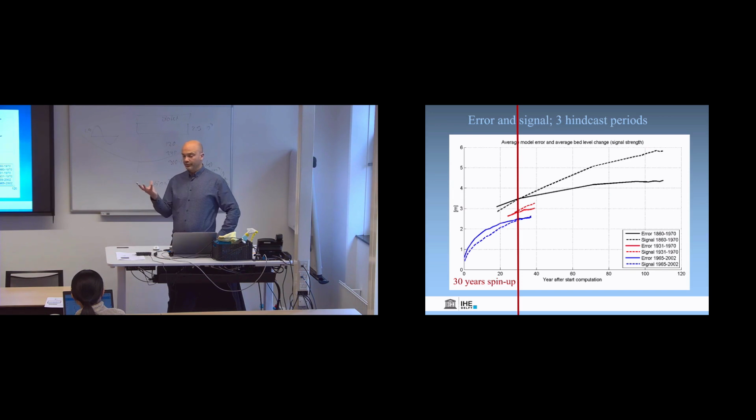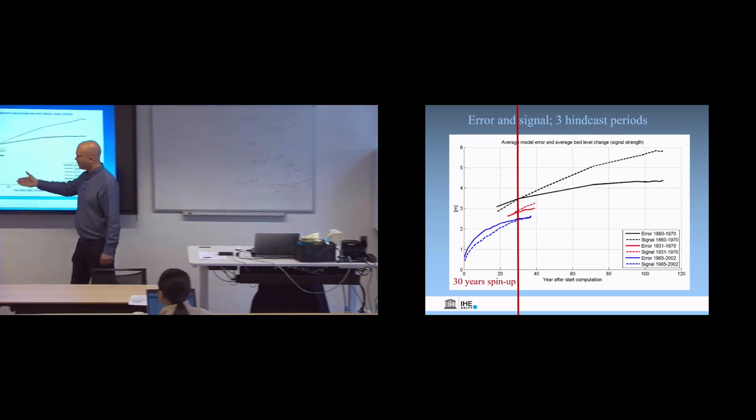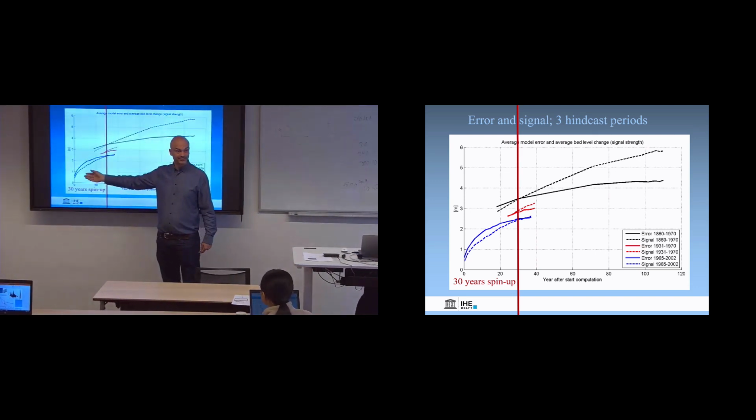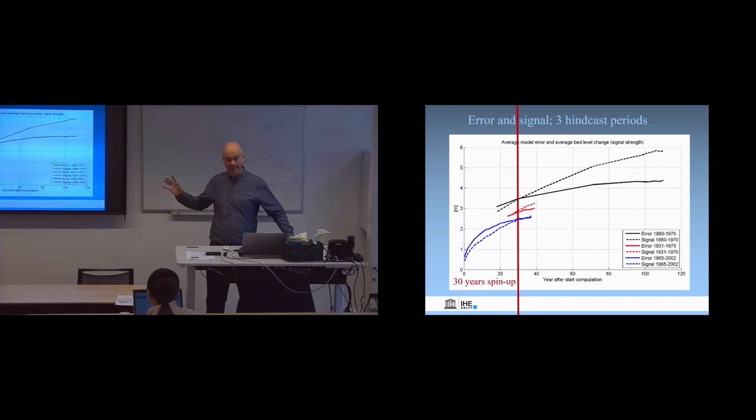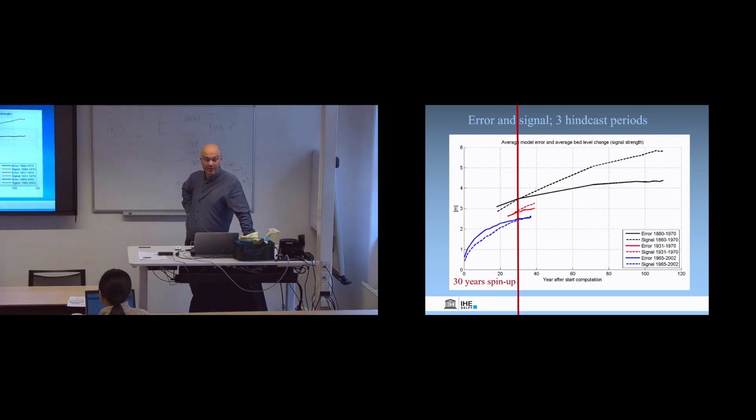Well, look, if your forcing conditions are relatively simple, you can also model them. And so the simpler your forcing is by a hydrograph that is always there, the sediment that is relatively stable, then your morphodynamic spin-up time would be maybe 10 years. So the morphodynamic spin-up time would depend on the system. For river systems, it would be typically smaller than for tidal systems.